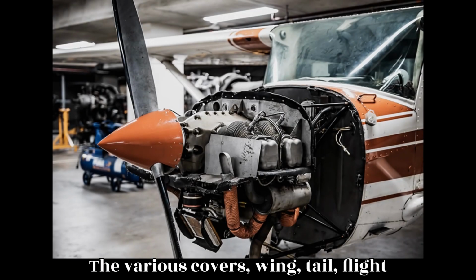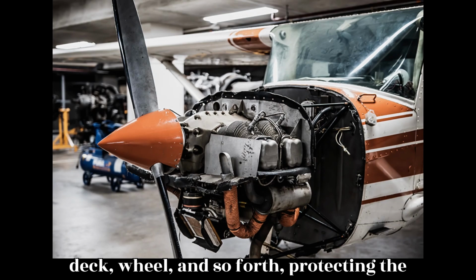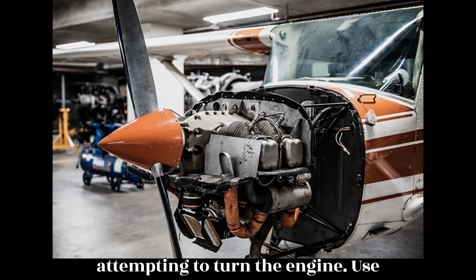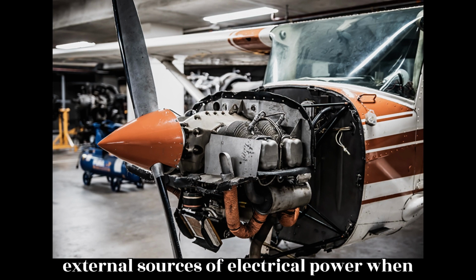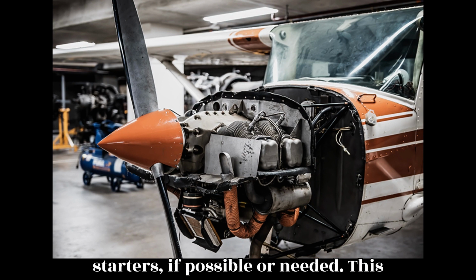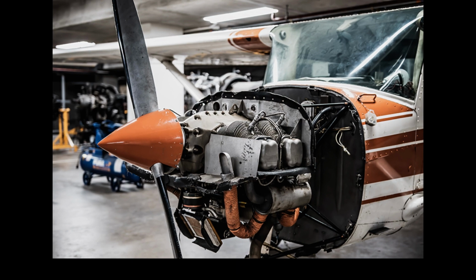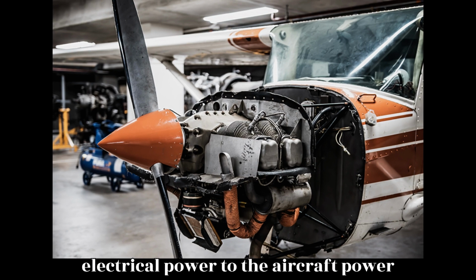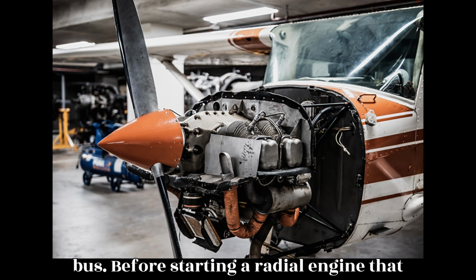The various covers, wing, tail, flight deck, wheel, and so forth, protecting the aircraft must be removed before attempting to turn the engine. Use external sources of electrical power when starting engines equipped with electric starters, if possible or needed. This eliminates an excessive burden on the aircraft battery. Leave all unnecessary electrical equipment off until the generators are furnishing electrical power to the aircraft power bus.